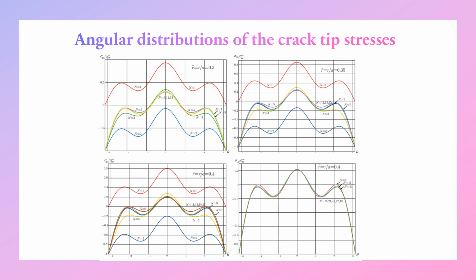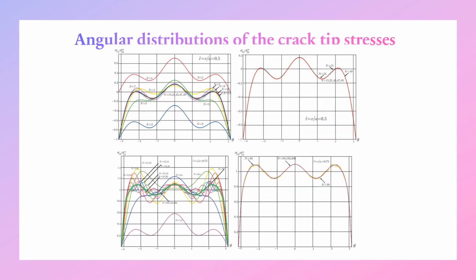The more distance from the crack tip, the more terms we have to keep in the truncated expansion. Then we can apply this knowledge for the experimental determination of the higher order terms in the Williams series expansion.